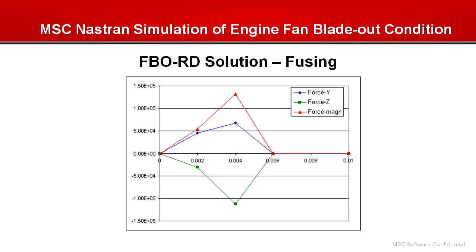What you see here shows the forces drop to zero when they fail during the fusing. Basically, there's no stiffness anymore. In the implicit rotor dynamics analysis, bearings can be really conveniently modeled using Nastran C-bush elements, where the stiffness coefficient can be directly input.